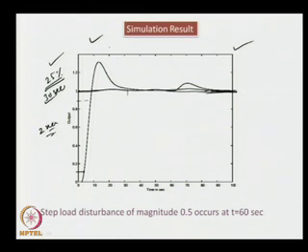The closed loop response is found to be quite satisfactory as far as performance of the closed loop to plant or process parameter variations are concerned, because we are designing a robust controller for the system based on gain and phase margins. Therefore, we may have a bit higher overshoot and settling time, but the overall response is always satisfactory for variations in the process parameters.